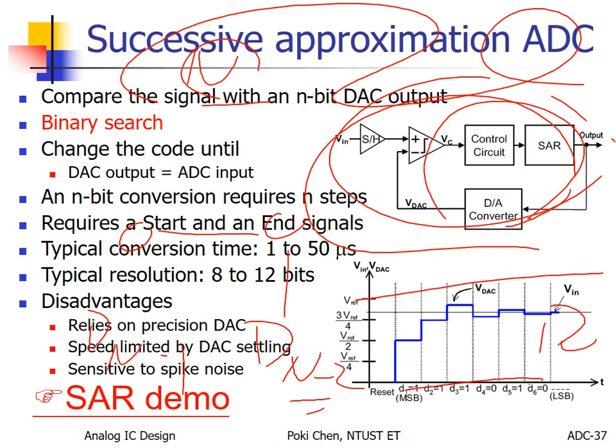So nothing is free. To speed it up, we can make it from cyclic operation to linear operation, pipeline operation, but the hardware will be increased by n times. So till now, I hope you fully understand not only the operation of SAR, but also of pipeline, because you simply change the cyclic operation to linear stages, one bit after the other. That is the so-called pipeline.